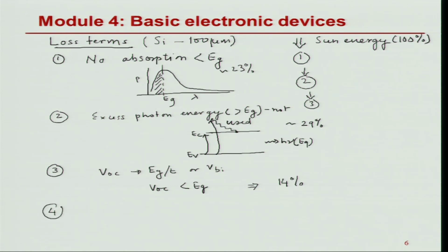I have the next loss, which is coming basically from the fill factor loss, because this fourth loss is there, because when we made our ideal device, we would have liked it to be this way, but we know the J comes in this manner, and that is because there is a fill factor. So, it is not the JSC times VOC that we get, we get a less value. So, if I take certain values from that, I will lose an additional 5% from here.